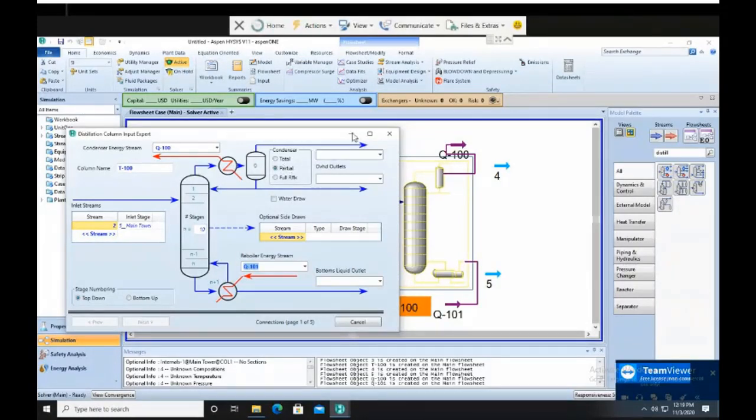So might as well just let it be in a vapor phase, and then whatever needs to be condensed, your product, put it in a liquid phase. But if you are very sure, in this case, this is a case of methanol and water, then we can actually use total condenser because we want to condense your methanol kat sini. Okay, so if you go for full reflux, everything would be in a vapor phase.